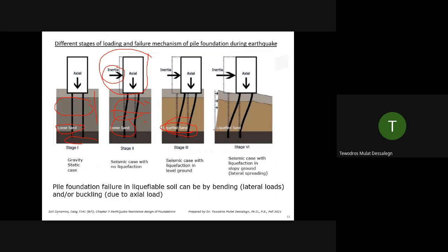Or in some cases, so you should design it. When you design this, ignore the soil entirely. That's what it means. Do not be dependent on the soil. Assume the soil will be liquid at some point. So when you design, the shear and the moment for the pile, that's what you have to consider. Assuming the worst case, you don't have any soil. If it turns into liquid, at least the pile will survive. Or in some cases, you may use a diagonal pile, bracing, not only vertical.